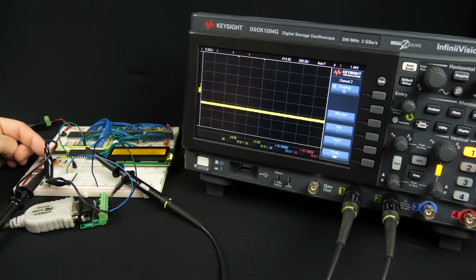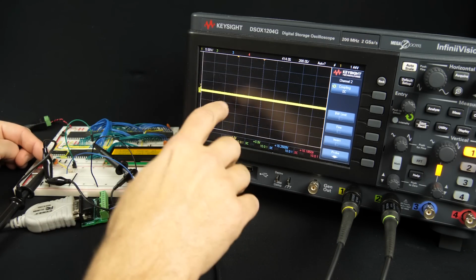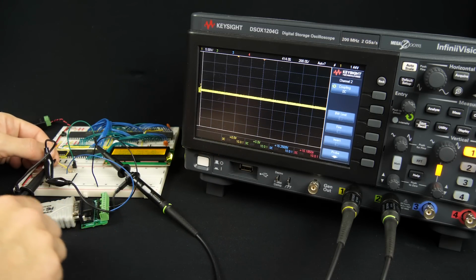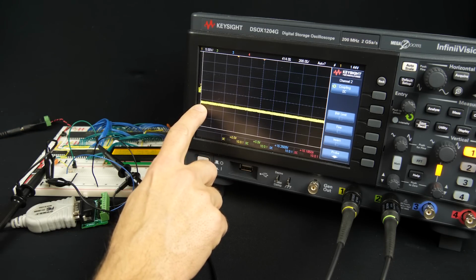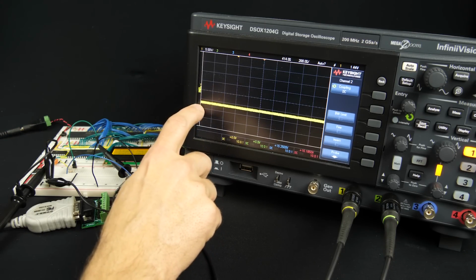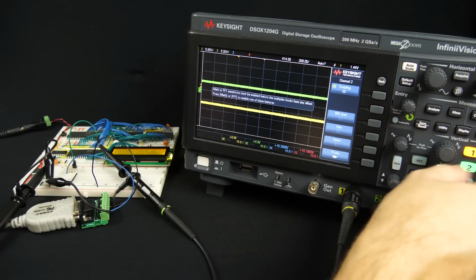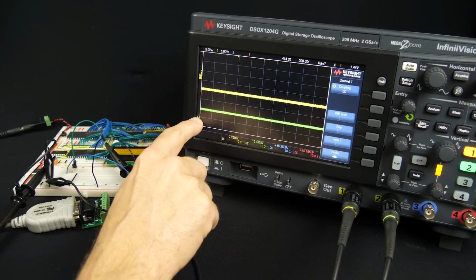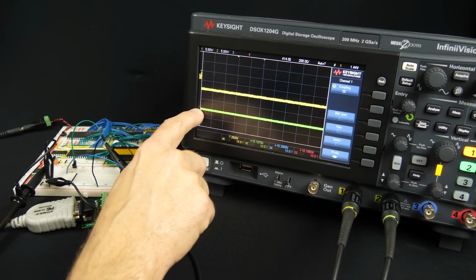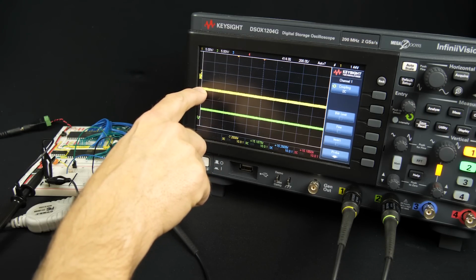So now I've got channel 1 connected to the RS-232 transmit data like before, and then channel 2 is connected to the output of the transistor. And we can see that, hang on, oh, we got a bad connection here. There we go. So we can see channel 1, the RS-232, is idle, sitting at a negative voltage like that. And if we look at channel 2, let's move that down here. There we go. Channel 1 will move up a little bit. So we can see channel 2. This is ground, and then each division is 5 volts, so we can see channel 2 sitting at plus 5 volts. Channel 1 is now sitting at a negative voltage.